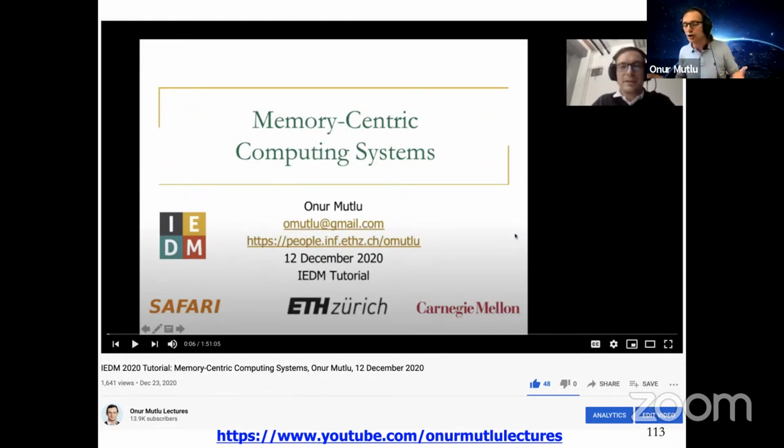And this disturbance phenomenon is actually very fundamental. It happens in hard disks. But hard disks have a lot of error correcting codes, so that they correct a lot of these errors before they supply data to you. It happens in flash memory today. Actually, we characterize flash memory a lot to understand those read disturbance effects. So it certainly also happens in phase change memory. It also happens in SRAM. It happens in any memory technology as long as you make the memory technology small enough, because you have interference between the wires, as well as between the wires and the cells. So certainly, it's vulnerable to the disturbance effect.